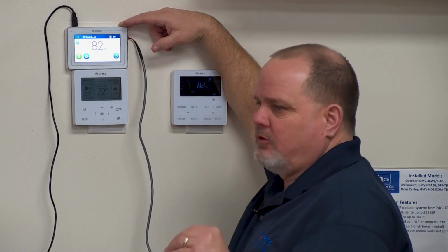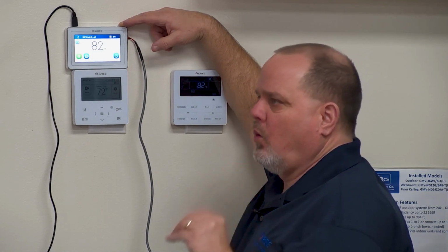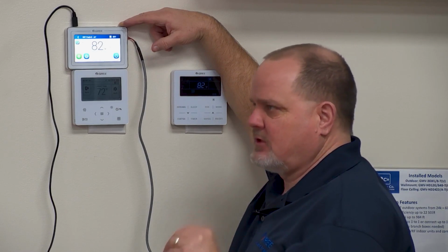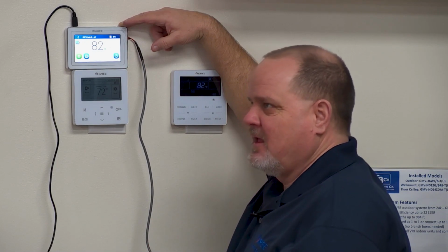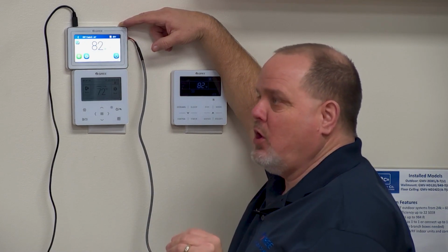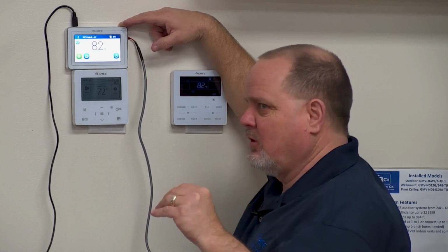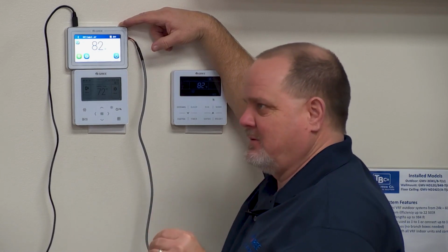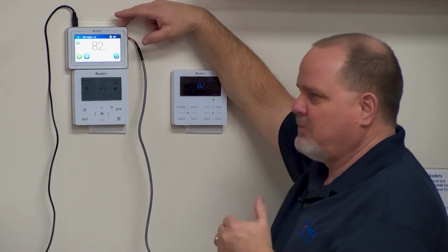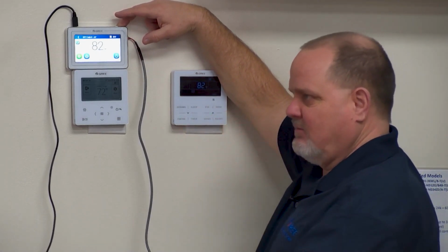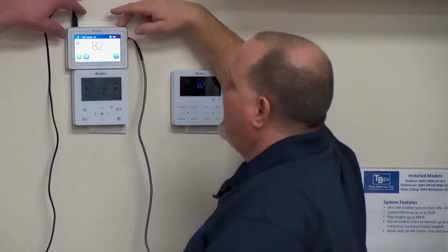The way variable speed works on these is it will adjust the blower speed according to the inlet and outlet temperature sensors and the EEV step and the load that's on the machine. So if you have very little load, you're going to have a lower blower speed. If you have a very high load, then you're going to have a higher blower speed. So I just want people to understand what variable speed really means in inverter-driven equipment, especially MultiPRO. All right, so now we're running.